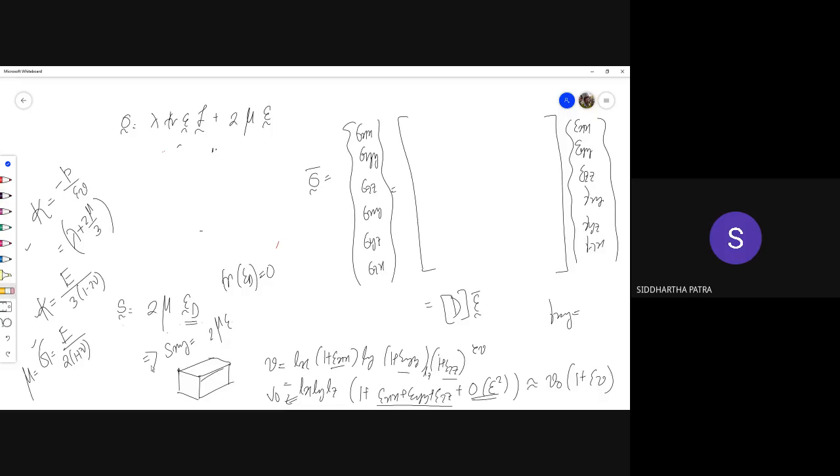As we discussed earlier, this is simply sigma xy. This is twice mu epsilon d xy, or twice mu epsilon xy, because the deviatoric part preserves the shear components. So mu times gamma xy, right? But as we know, sigma xy is G times gamma xy. That eventually gives us mu equals G. So gamma xy, as we know, is twice epsilon xy.